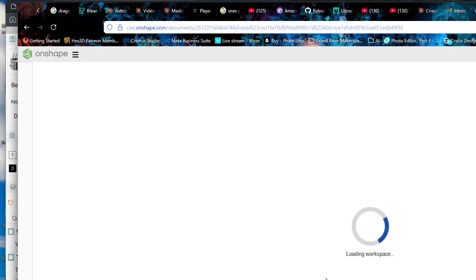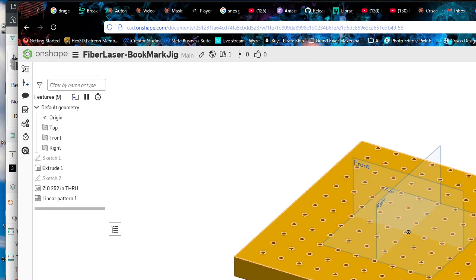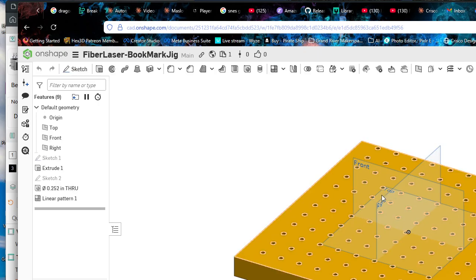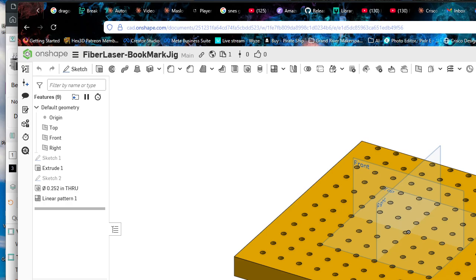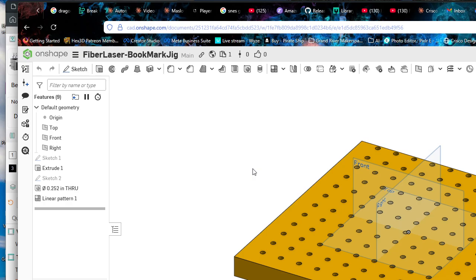Now, if this model saves a DXF file to Fusion, or an STL file. Yeah. Now, Fusion can import that. STL files really are hard to work with. Fusion can do light STL. To take it from Onshape to Fusion, if I wanted it to be a CAD file, I'm going to export it as what's called a STEP file, not an STL file.